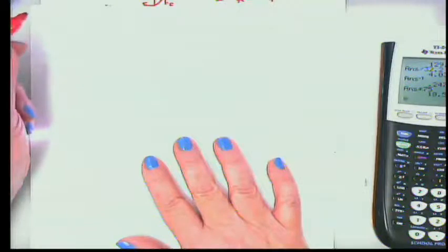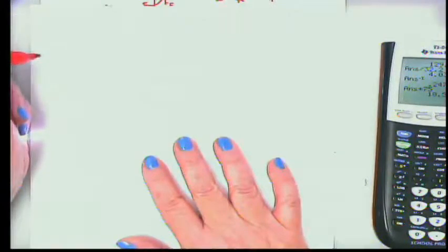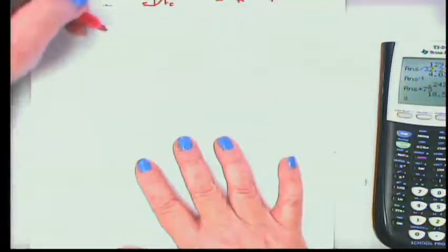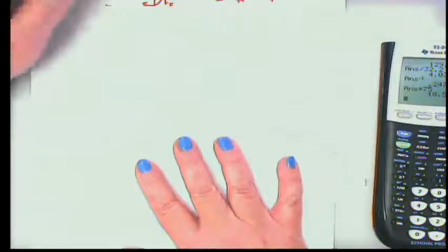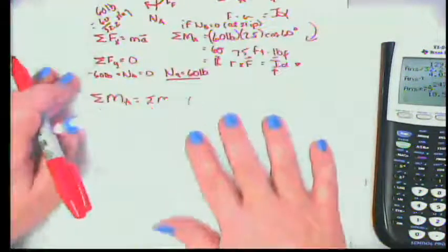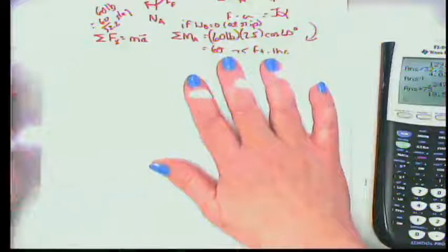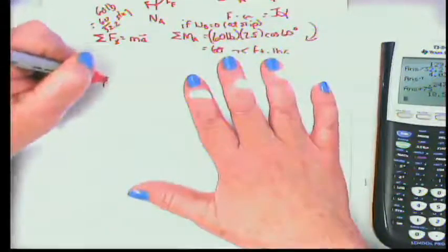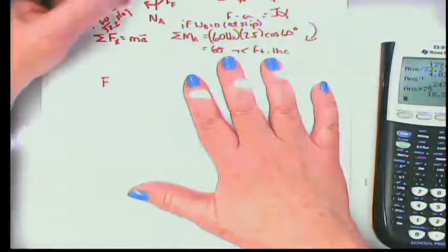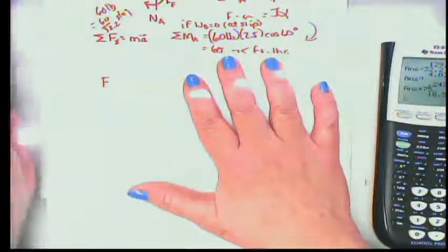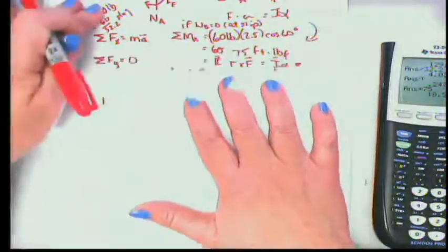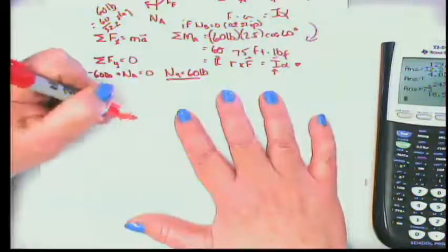All right, so we want to determine, given that is the maximum allowable acceleration, the corresponding minimum required coefficient of static friction. Well, if we go back to our summation of forces in the x direction, we know that when this slips, that's going to be the only force, equals mass times acceleration.